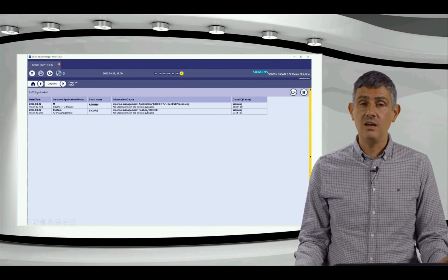For example, a bus bar. So we will see here we have a horizontal bus bar. So we select it, and then we drag and drop it here. And then it is displayed here. Now, we want to have maybe a disconnector connected to this bus bar. So we select now this disconnector, drag, and we drop it close to the bus bar. When we drag and drop an object close to another object, then the system tries automatically to connect it, which is fine. It saves us some work.